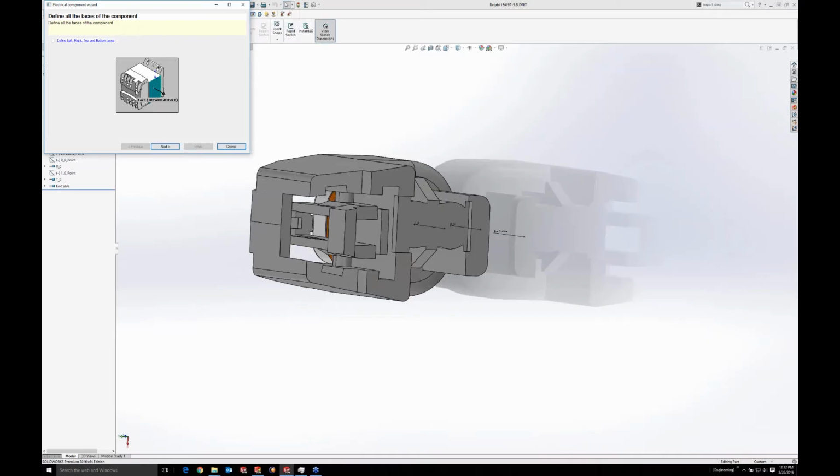So you'll see a DIN rail component here. I can define the left, right, top, bottom. Not concerned with any of that. Here we have some built-in mate references. One of them is for a 35 mil DIN rail, one of them is for things that mount to the back of an enclosure, one of them is for things that mount to the front of an enclosure. Well, that's not how I'm going to do my mate references for this, so I don't really care about any of these either. The last one is create connection point or create connection point by reference.